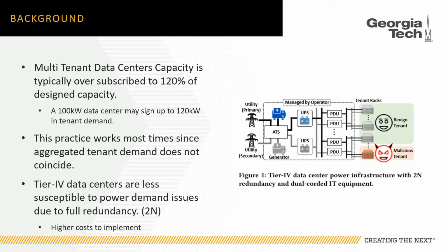So even if the tenants' total demand is higher than the design capacity of the data center, in practice, that demand will not be aggregated or present at the same time, meaning that there is an opportunity to have less than 100% coincidence in those loads.